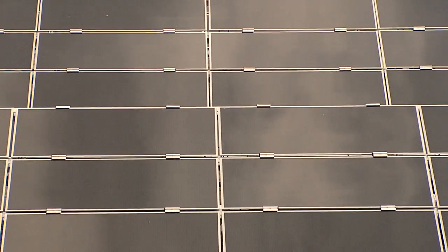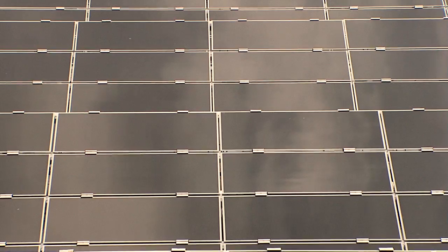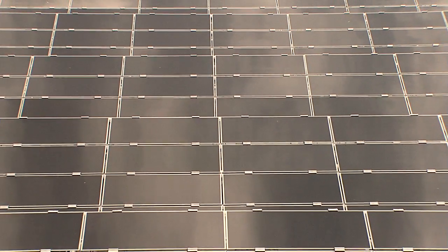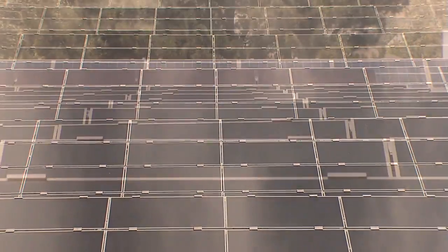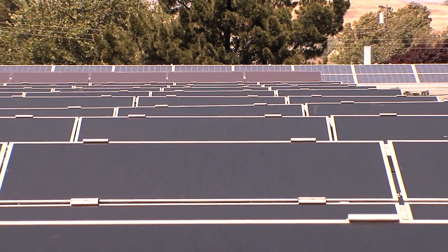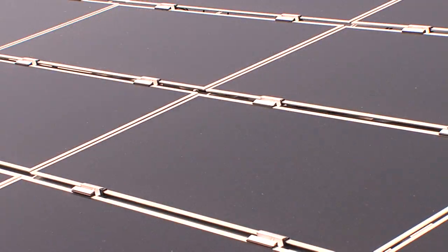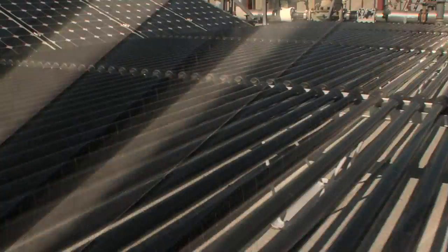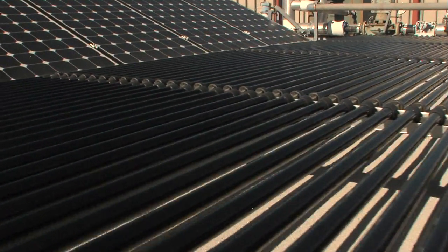And when it's performed at the panel level, each panel is now an individual contributor, power generator, and is independent of its neighbors. So whether the neighbor is shaded or in full power, it has no effect on the adjacent panels, and there is no string effect. That means you can mix and match panels of different types, or if you have a warranty replacement in the future, you can use current generation technology rather than having to redesign your system around a new panel type.